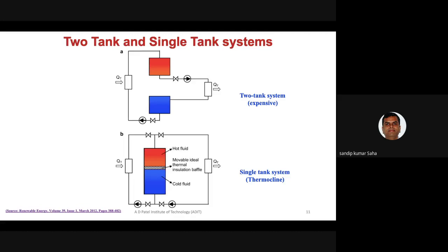Mostly we will model this phenomenon using natural convection, because although there is flow at the top, we see that Grashof number divided by Reynolds number squared will be greater than 1, so forced convection will not be the dominant factor. So mostly it will be based on the natural convection approach, taking care of it through density difference. That means I have to incorporate this physics in my computational model.